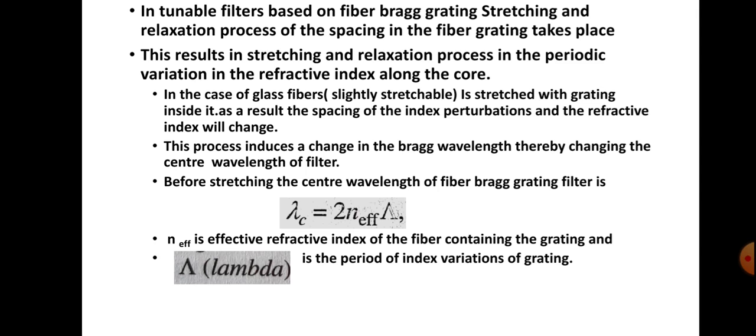Usually the grating will be inside the core of the fiber. When we stretch the fiber, the grating structure inside it stretches. As a result, the spacing of the index perturbations and the refractive index will change. When we stretch that fiber, the grating structure changes. As a result, the periodic changes in the refractive index also change. This process induces a change in the Bragg wavelength, thereby changing the center wavelength of the filter.